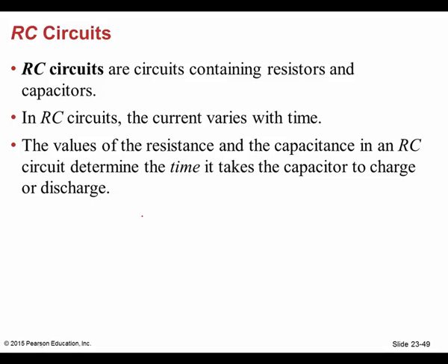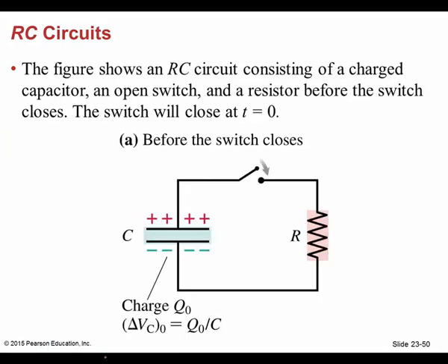Now, one thing about resistors and capacitors in combination, they are called time circuits, because when you combine a farad with an ohm, when you work the units out, you get a second, okay? All right, that's really cool, isn't it? In other words, you get time. And you say, well, how does that work out? Well, folks, it does. Just take the units and start working it out, and you'll see that when you combine the units together, everything cancels out except for the second, okay? And so an RC circuit is actually a time circuit, okay?